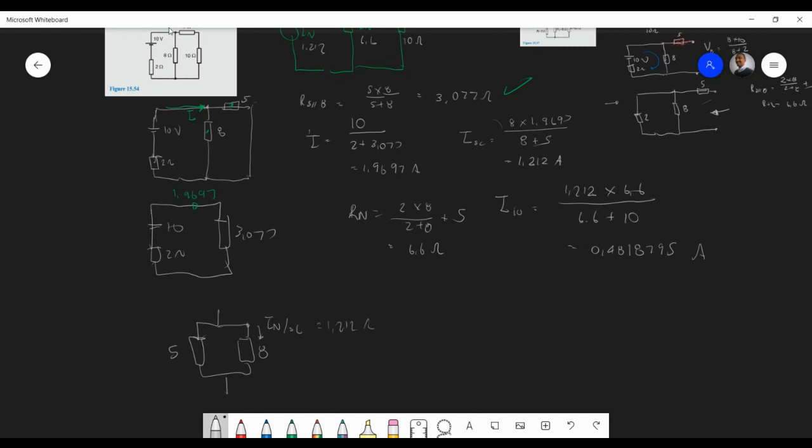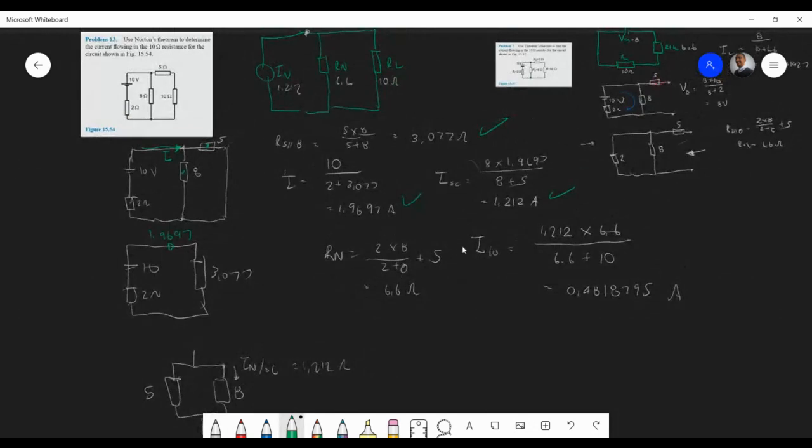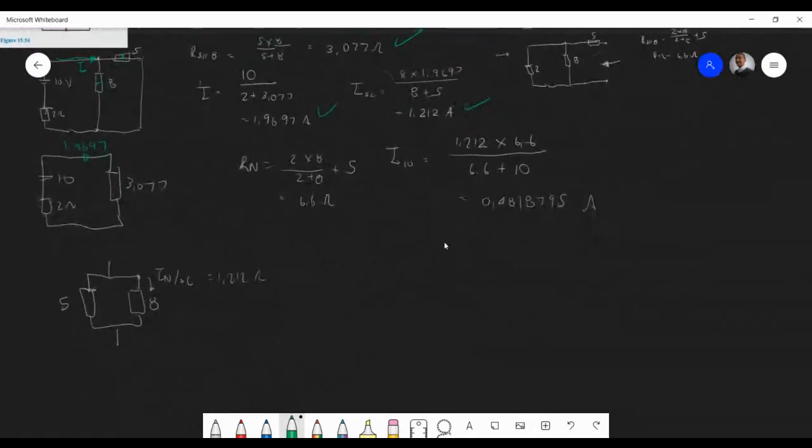Pauline, are you following so far? Yes, sir. Great. The next step is exactly the same as the Thevenin. So we're going to remove all the sources, like this. What was it again? It's 8 and 2, and remember that 5. And we've shorted this now, looks like that. And then we do exactly the same thing.